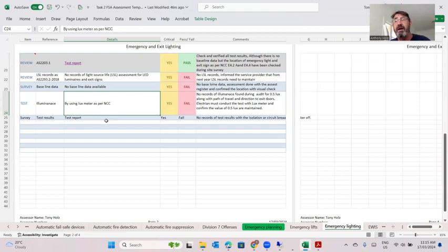Maybe, maybe not. That's our job as an assessor to determine if that type of system's been installed, whether there's enough lights, whether they're the right type, based on AS 2293.1 and those pictures that I showed you before, by design. Or we go back to the owner and say, no, it fails. I want you to go and get that design.